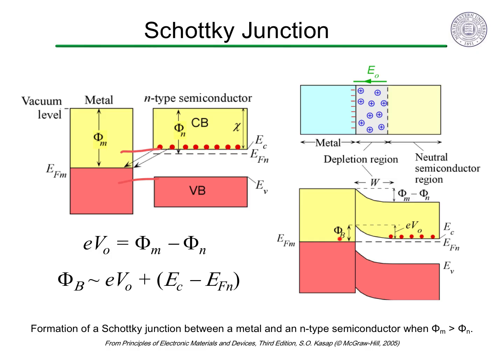This offset between the metal Fermi level and the bottom of the conduction band, phi b, acts like a barrier for electrons trying to go from the metal into the semiconductor and is called the Schottky barrier. Notice the Schottky barrier to the conduction or valence band depends on where the metal Fermi level is relative to the semiconductor bands.